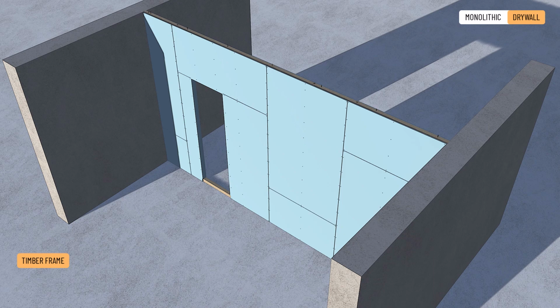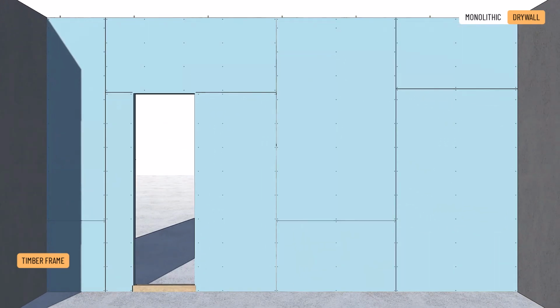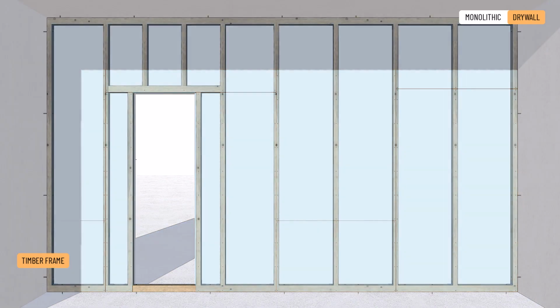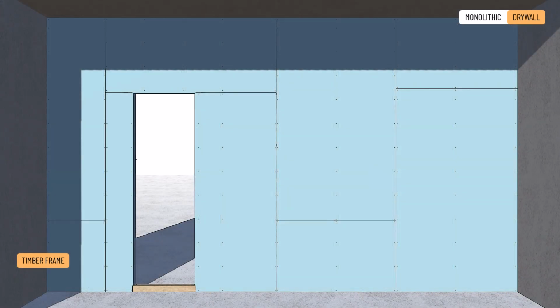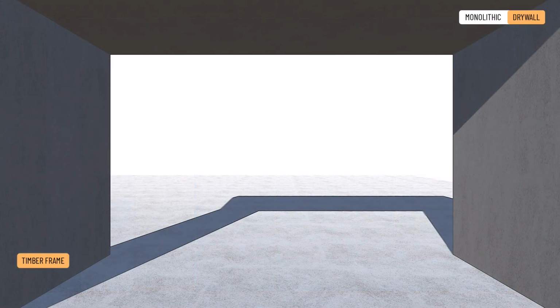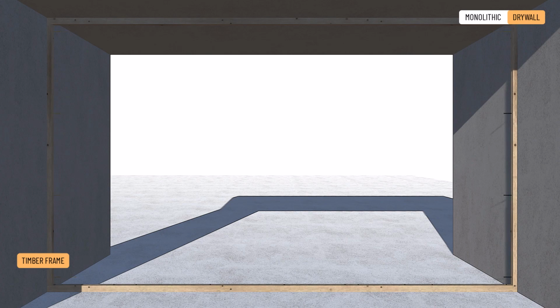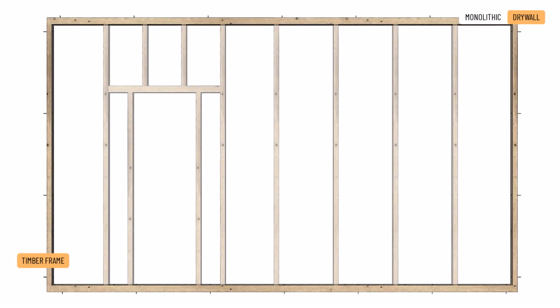Timber frame structure. Today, the more traditional approach to drywall partition walls uses wooden studs for the frame, typically with a 30-50 mm profile. Plywood is an alternative to using planed timber. The horizontal plates are typically larger cross-section beams, for example 50 by 50 mm, between which the vertical studs are placed, screwed or nailed.